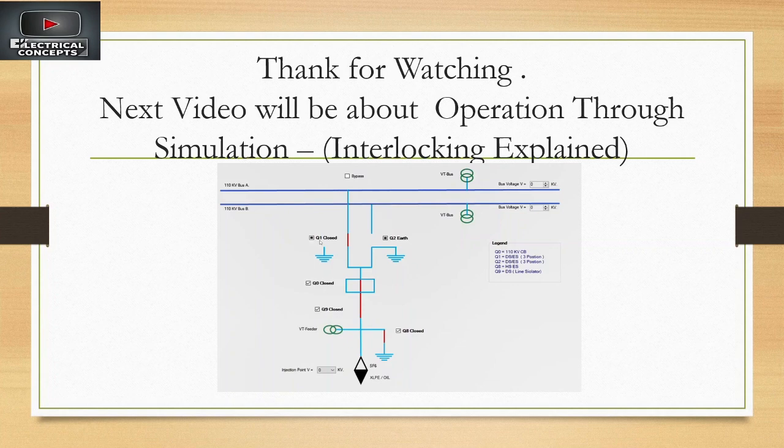If you do a workaround after casting of the slab, this will compromise the quality and is not a professional approach. So make sure that all the openings match the system of the switchgear. For the capacitor and auxiliary transformer, you can also get the input from the manufacturer and start designing its foundation. Normally the manufacturer has this information readily available because they produce thousands of units with the same weight and dimensions. So they can give you the design at an early stage for the civil input.